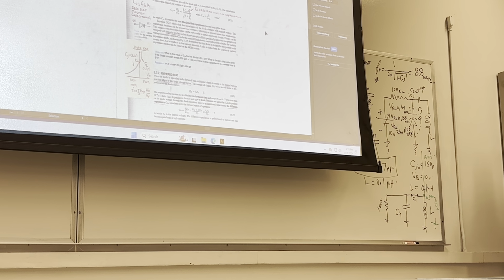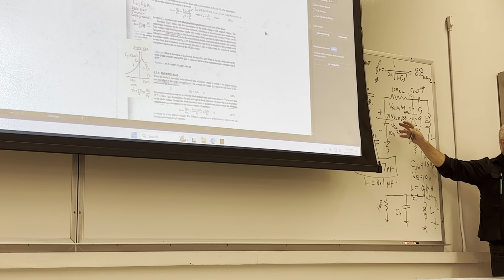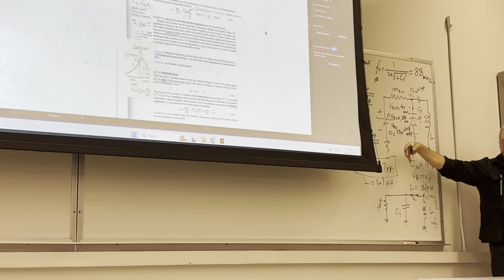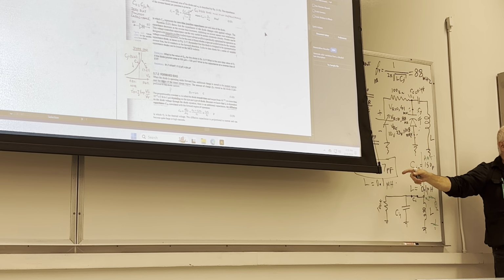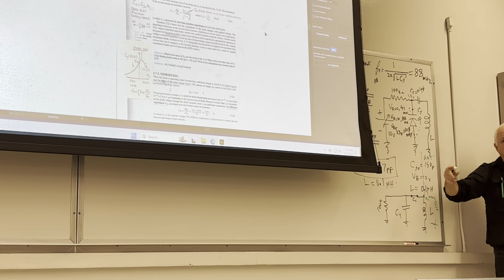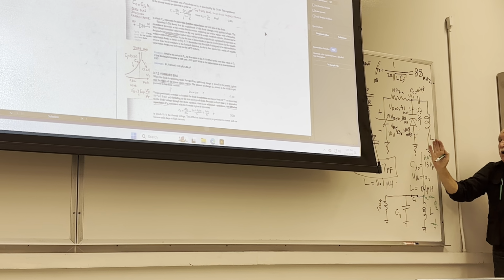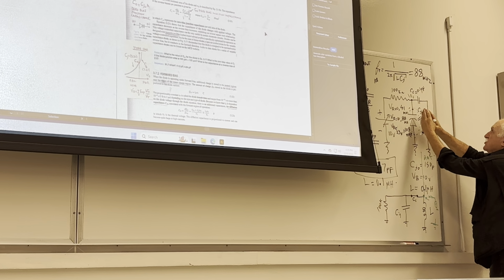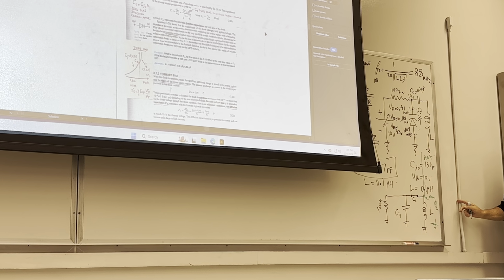So automatically you can say, if this voltage source happened to be a digital to analog converter, because D to A converters produce analog outputs, isn't that right? So if the D to A is scanning digits up, and the analog is going stage up, you are basically sweeping or scanning the radio spectrum. So once you pick up a signal from a station, you stop at that moment.